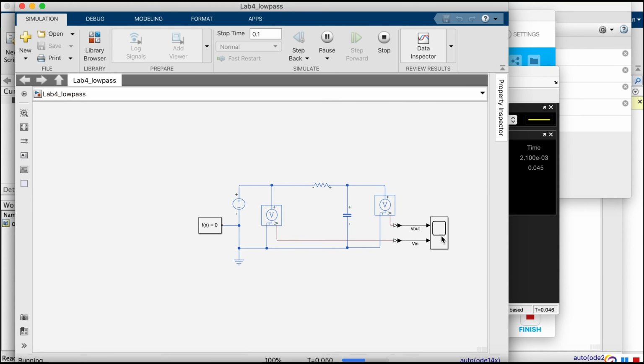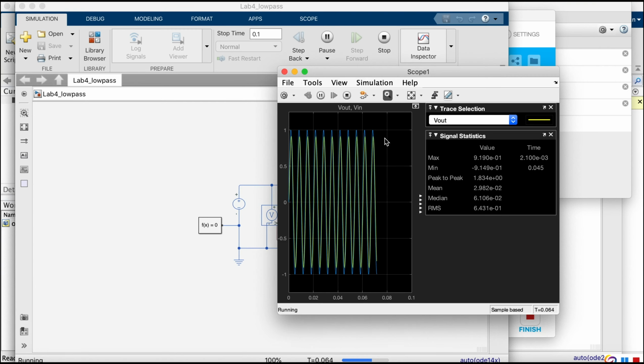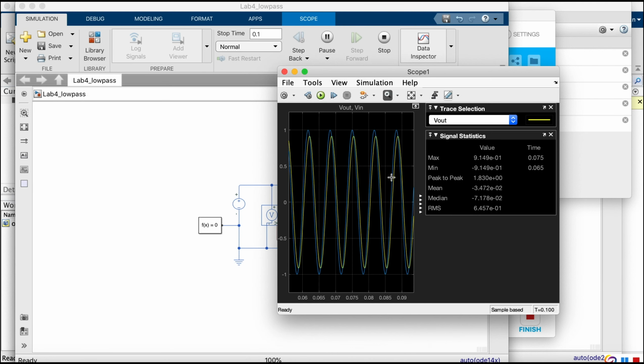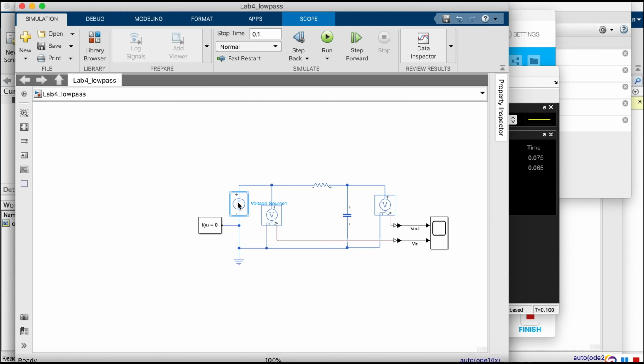And then you'll see that it's coming up. For example, at 150 Hertz, zoom into the last part and you'll see that this maximum, the amplitude, would be 0.9 volts. And yeah, then repeat these for different frequencies, find different amplitudes, and complete the graph.